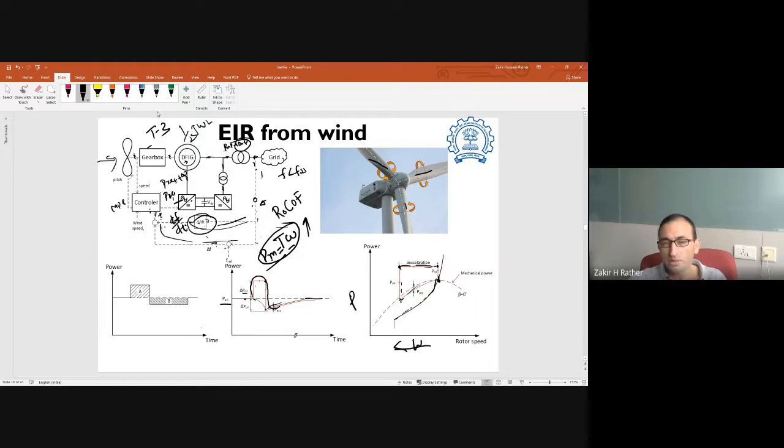So net power after this inertial power release is going to be less from the wind turbine, and that is how it works in a wind turbine. But it has to maintain this energy balance. Whatever additional power it generated has to be taken back so that its speed regains. This is not the case in synchronous machines because the governor comes into the picture. Additional power is fed from the backside mechanical side, which does not happen here, and therefore here in the wind turbine generator, after providing the inertial response, it needs to take back that energy to gain its speed to its pre-disturbance value. That is how wind turbines can potentially, and do in some parts of the world, participate in inertial response.